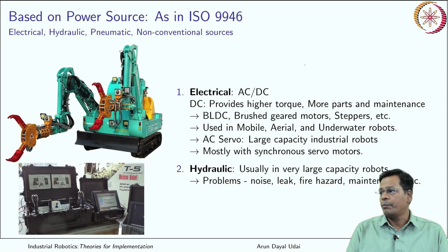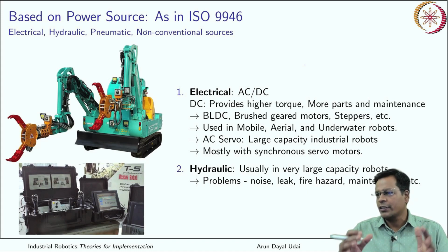Okay, and then everything comes at a cost. Even this one, because to generate hydraulic power, it has to have a hydraulic power pack which keeps a motor running continuously, that keeps on developing the pressure for the actuators. So it creates a lot of noise, and it uses oil. Obviously there are some leaks which can happen, and because it is oil, fire hazard is there.